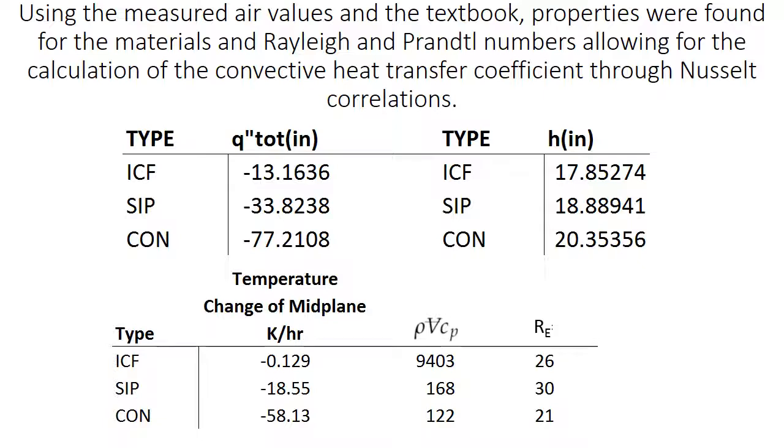And so because the ICF maintains its internal surface temperature so close to the internal ambient air temperature, Q is very limited, and because it goes down, even though the H is about the same, the temperature gradient is so much reduced due to the temperature change from the wall to the ambient air.